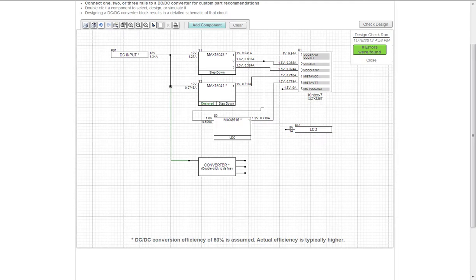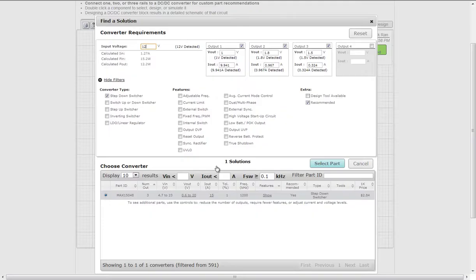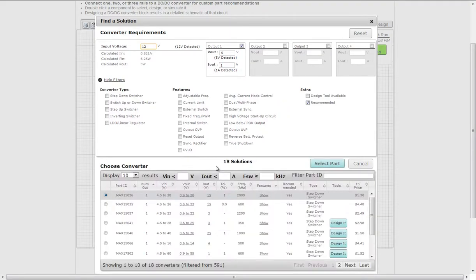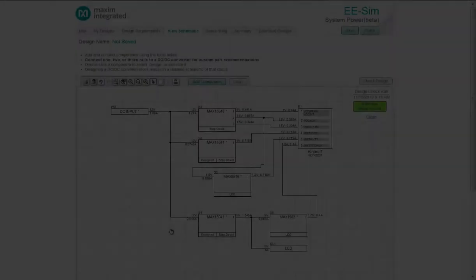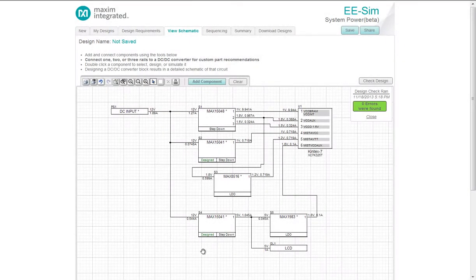Continuing my connections. Note I am using only one output from the 3-output converter. The tool automatically uses the one connection in the drill down menu and changes the converter to a single output converter. Defining my final 2 converters. Finishing my design. I should have saved it if I've not already, so I will save it now.